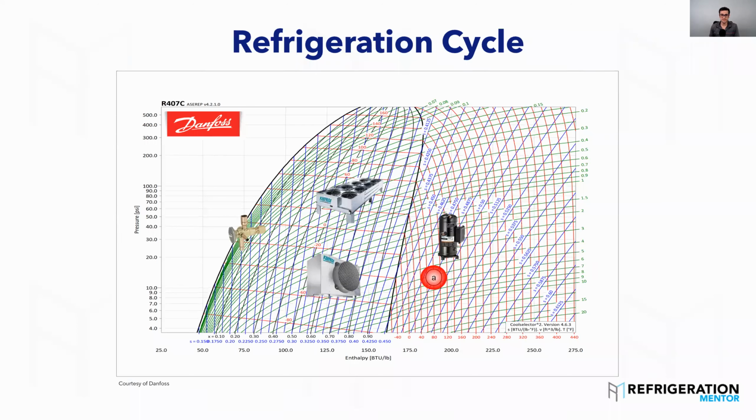I've seen it before. So, okay, this is another enthalpy diagram. This is from the Cool Selector 2 app. You download it on your computer. You can get any manual from Danfoss there, but this is the enthalpy diagram that we talked about earlier. I want to walk through how the refrigerant is going through a system. So here's the refrigerant. Think of this little red ball as the refrigerant.